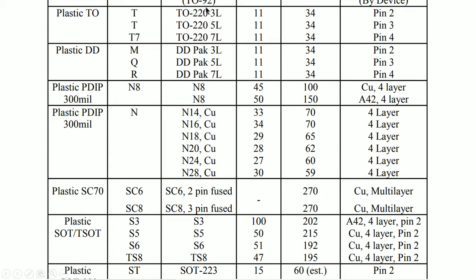You see here at the top, I am sure several of you must have come across these TO 220 packages. TO 220, instead of the old TO 3, has the same die and chip mounted in a plastic case. You understand, no? Plastic with a small heat sinking base attached to it. So, what was 3 suddenly becomes 4 times as much, because the amount of area available for contact is much less.